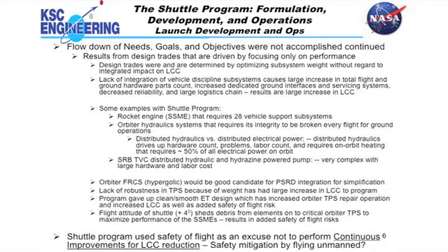The SRB TVC has a distributed hydraulic system that's powered with a hydrazine system, very similar to the ones that are in the orbiter. And we've made several attempts to try to get that simplified, but again, we've frozen the design, as Tom says. So the next systems ought to avoid these complex designs.